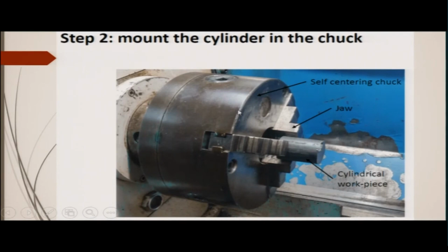Here the 3-jaw chuck in the close view we can see, this is the workpiece, all right. The value will be added to the workpiece, meaning that you will have to have the surface made, proper surface made, then the conical head has to be made, so that the gear can be cut, because right now it is the turning lathe, it is the lathe machine on which the work is going on, but ultimately we have to cut the bevel gear, and the bevel gear will be cut on the milling machine.